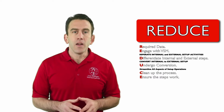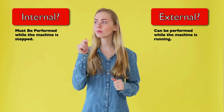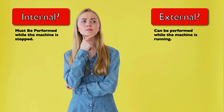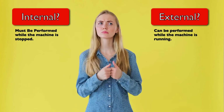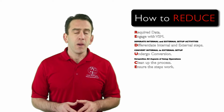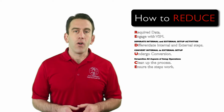With that being said, one of the contributing factors of a long setup time is the confusion associated with internal and external setup times. This often results in many changeover tasks that could be completed while the machine is running not being performed until the machine is stopped. As such, setup times are much longer. So, how do we reduce setup and changeover times? Let's look at a high level of each of the stages of the reduce methodology.